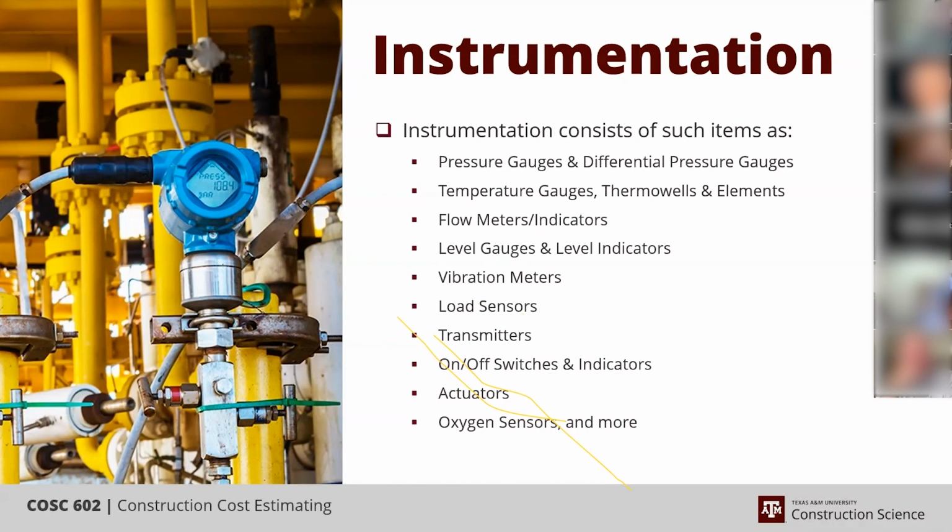So the thermal well is actually taking the heat, enduring the environment of whatever it's installed in, but the element is what's sensitive to the change in temperature, and then that element sends the signal through a wire back to an instrument that will read it. And so the instrument could be some distance away from that particular thermal well and element.